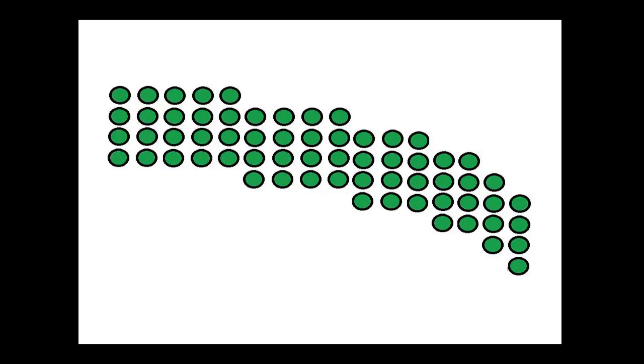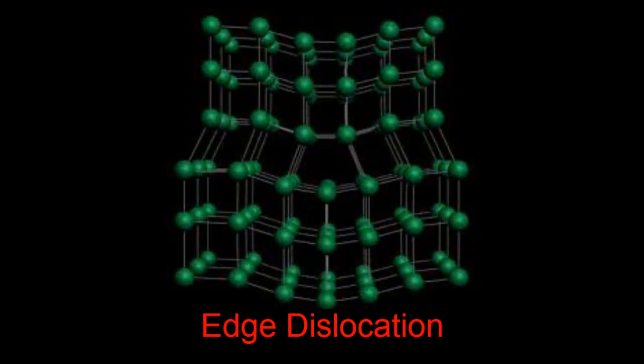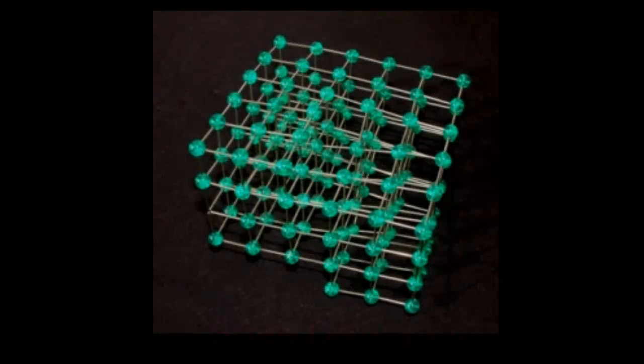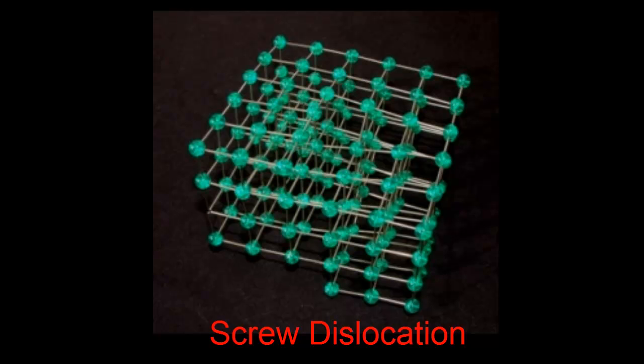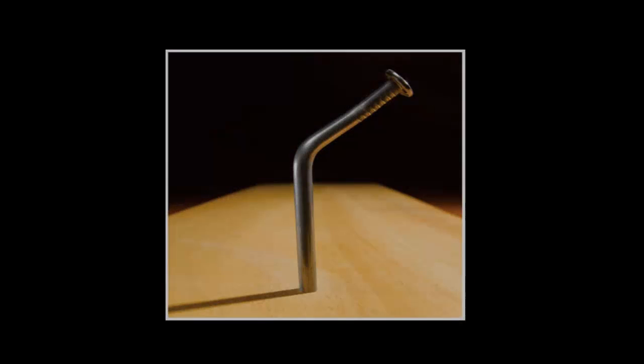In plastic deformation, when a load is applied to a material, it deforms. However, in plastic deformation, it does not return to its original shape. This is due to microscopic dislocations, such as edge and screw dislocations. When these dislocations are introduced into a lattice, they permanently alter the structure of that lattice. Thus, plastic deformation is a permanent deformation.